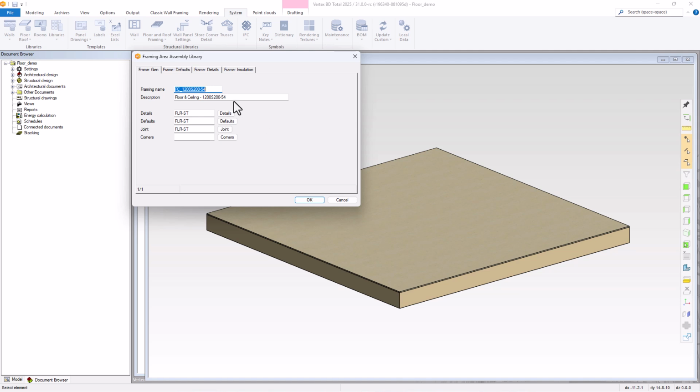In this example, we will create a framing tool for use with our custom floors. Enter a new assembly name and ensure the name is unique. Add LWC for lightweight concrete to the end of the name and in the description. Leave floor structure settings as they are for all 4 fields for the floor structure details. Under the Frame Default tab, change the spacing to 12 inches on center as the default. Leave other settings the same.